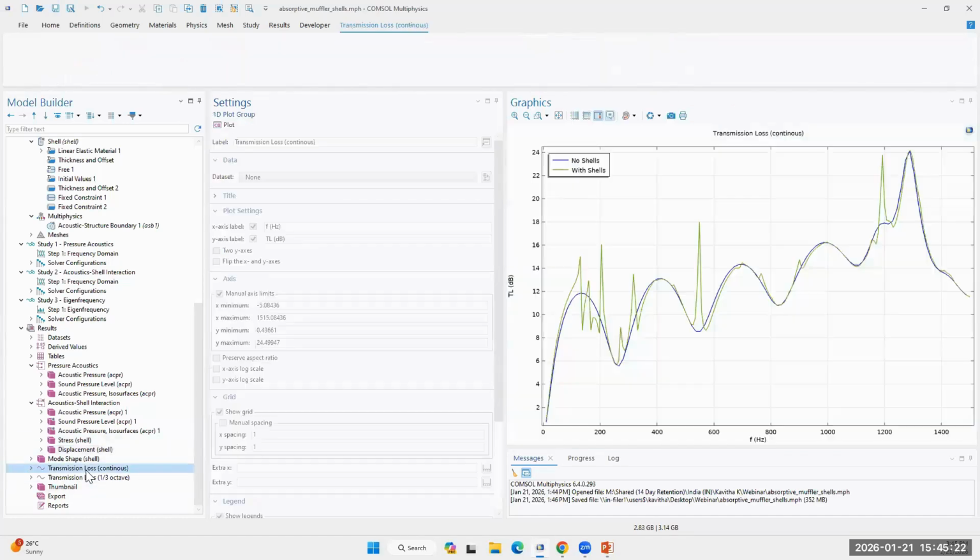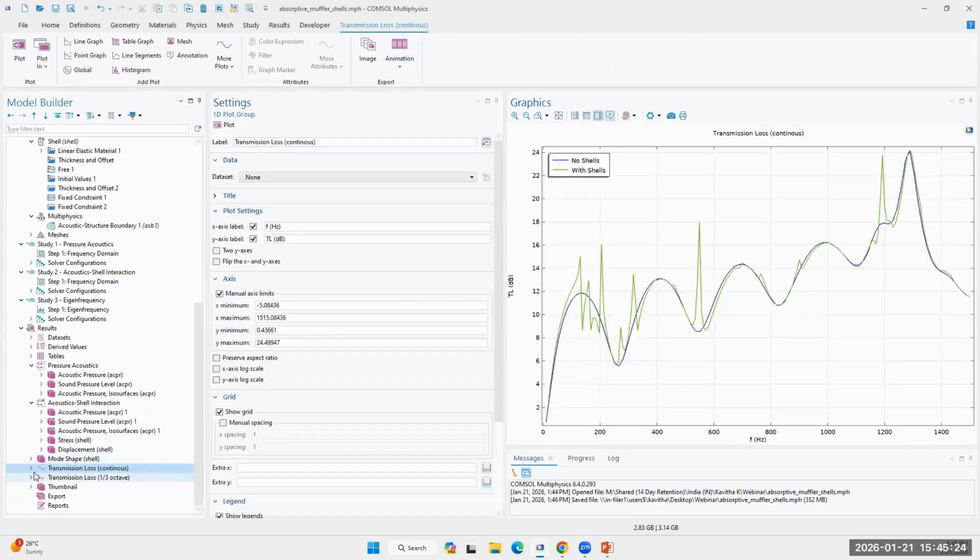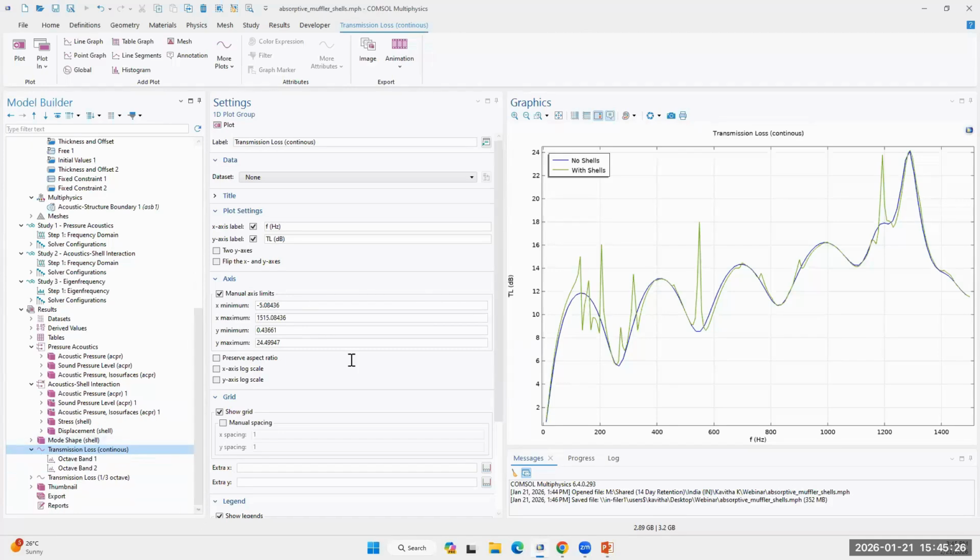And further, you can visualize the transmission loss characteristics. You can plot the transmission loss characteristics here. You can see a stronger effect on the transmission loss if there are structural vibration sources. Strong acoustic sources may appear again at the muffler walls as well. The structural sources are not accounted for here, but you can account for them as well.